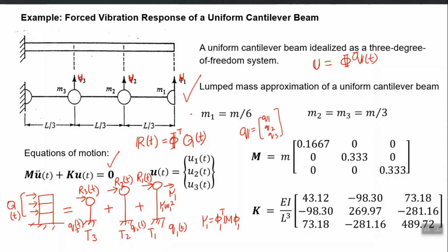Although we have formulated this modal analysis, or modal RHA, for the forced vibration case, we will see that it is valid for free vibration calculations also, because the right hand side, or the modal forces in our modal single degree of freedom system equations, will be 0 in this case. Therefore the same framework can be applied to free vibration also.